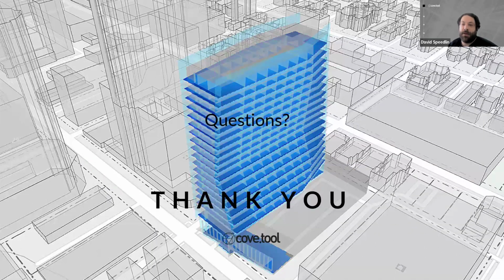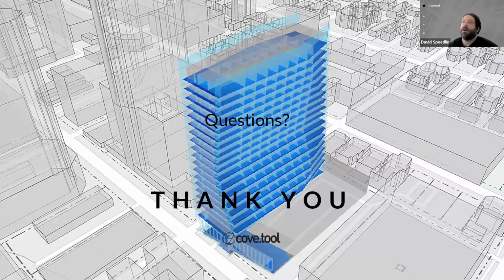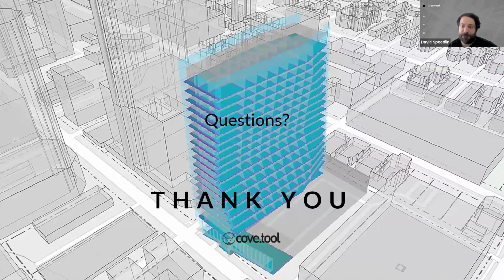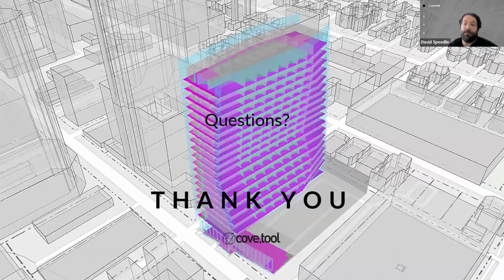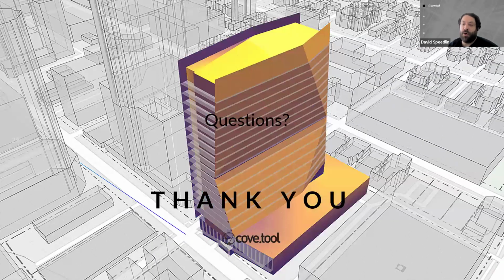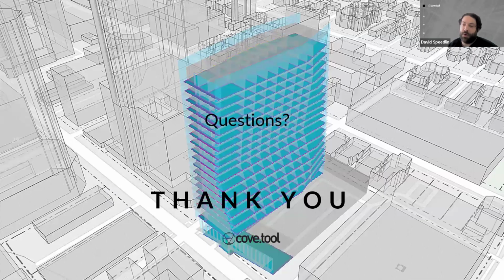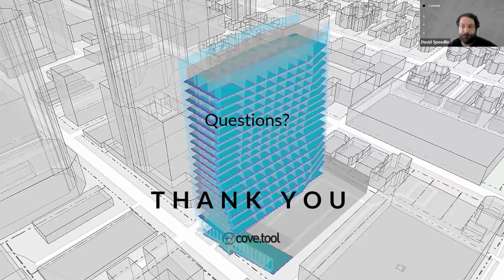The easy way to check to see if there's an issue with something is to export per view. But in some instances, drawing tool, the way that it creates its rooms is by using rooms and then closing the space around it. So sometimes it will over analyze a space and add an extra wall or remove an extra wall. And in that case, you will have to go into drawing tool and correct it there.